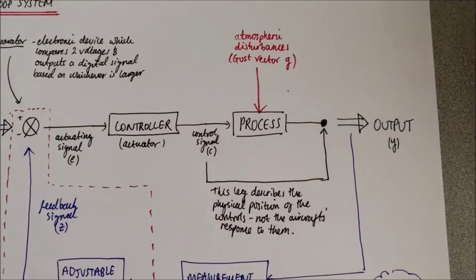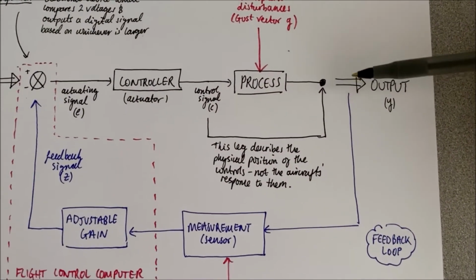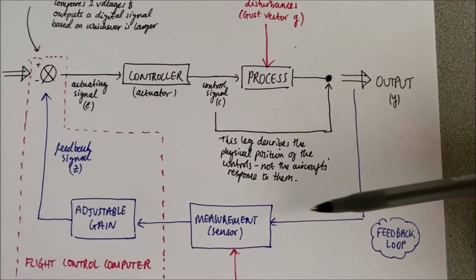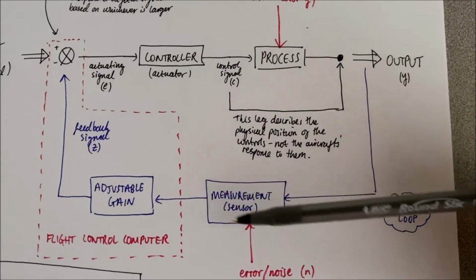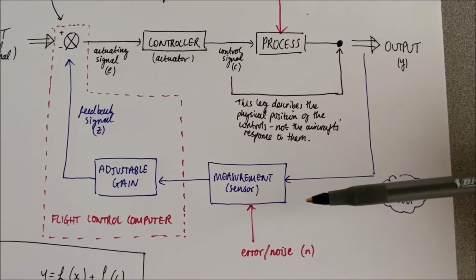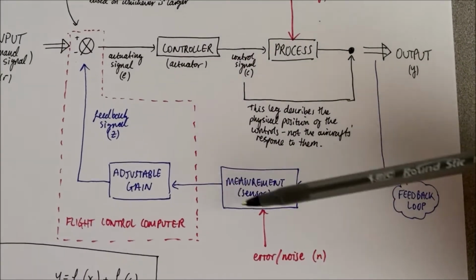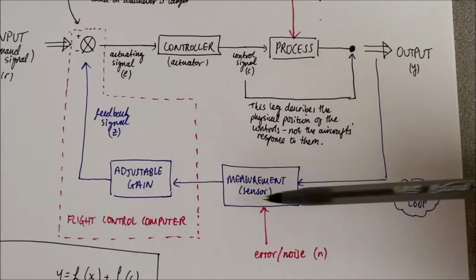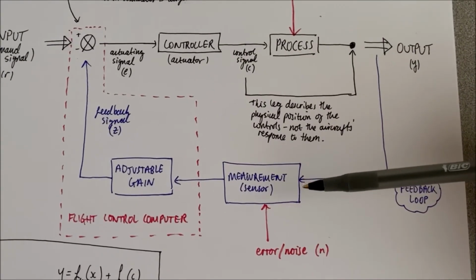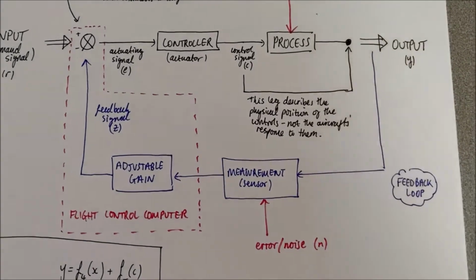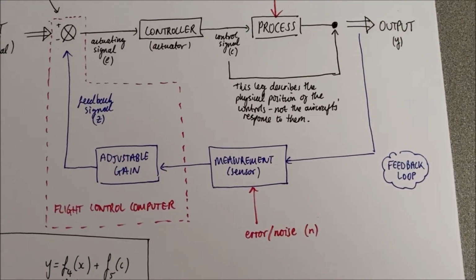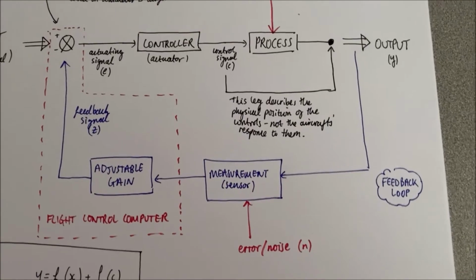So this then formulates our feedback loop to our control system, following this blue line down in here. We have a measurement of some parameters. Now again, this is quite an important piece of the jigsaw here, because the precision or the accuracy of our measurements is obviously going to impact how effective our control loop is.